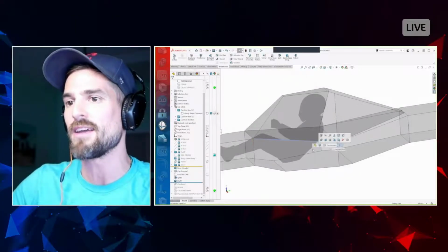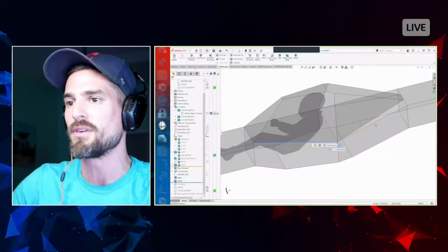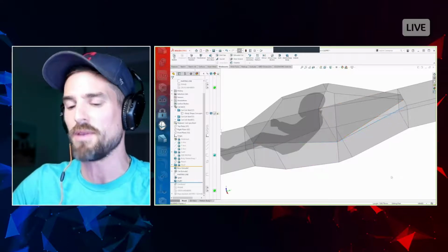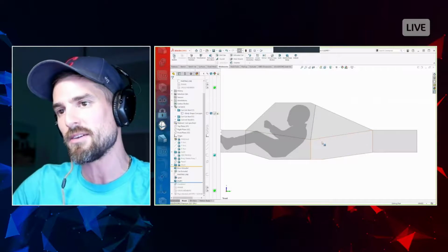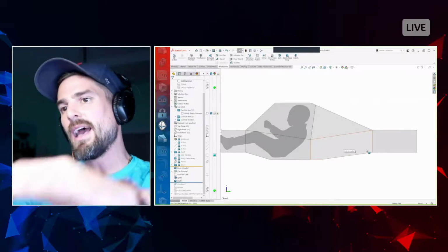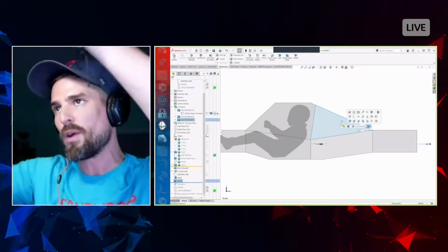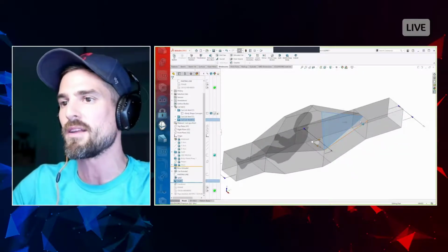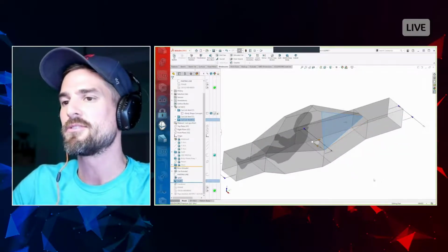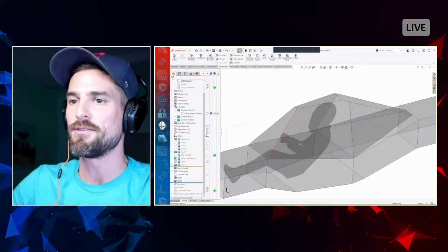This one, because the edges match up and stay neutral. But this one over here, it separates because if you take a look at the side, the neutral plane is actually an angle that's coming all the way down here. And this theoretical surface where it intersects that angled plane is where the pivot point is, which cuts it inside of that edge. Yes, so I agree with all of that.